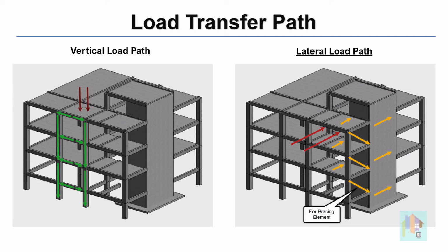Any load applied on any part of the structure will travel through the load path and finally end up in the support. Now, if there is no stiffness somewhere in the structure, which is a part of a load path, then that load will not be transferred to the connecting member. This creates an unstable condition which might be critical for structural integrity.